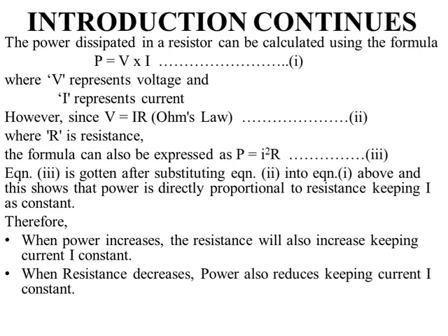The power dissipated in a resistor can be calculated using the formula P equals V multiplied by I. We say that power dissipation P equals VI, where V represents the voltage and I represents the current. However, since V equals IR, remember our Ohm's law, since V equals IR according to Ohm's law, we can decide to substitute V as IR in our P equals VI.